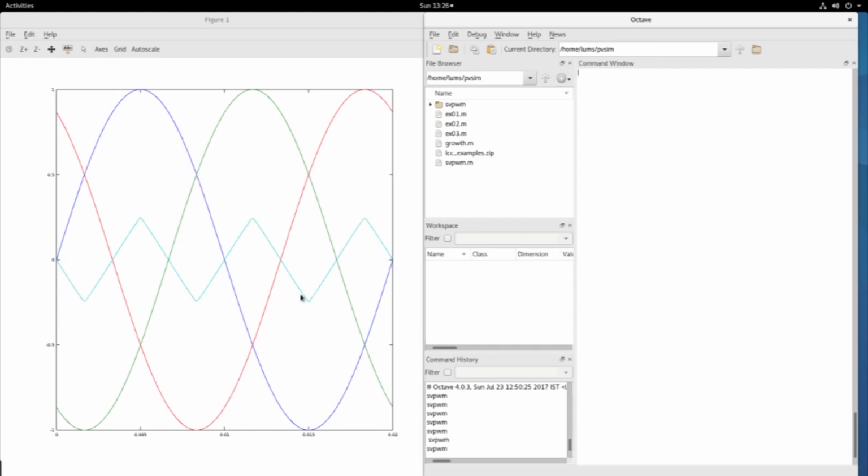Now this wave shape is actually a third harmonic. You will see that there are 3 peaks within a cycle. So that is a triplen. So I have the triplen here. Now what do I do with this triplen? Let us say I have the fundamental. This fundamental minus this triplen.